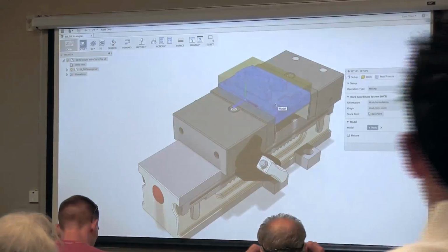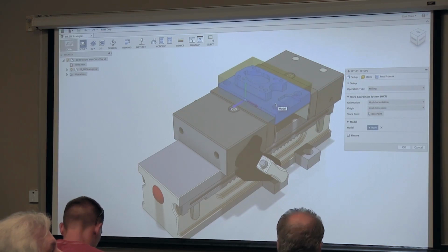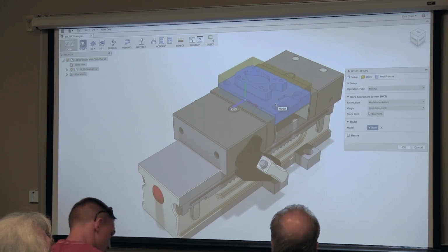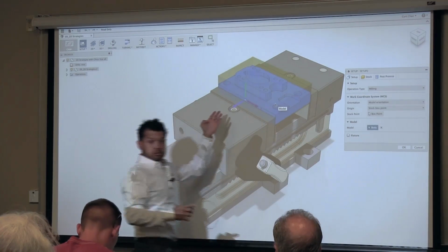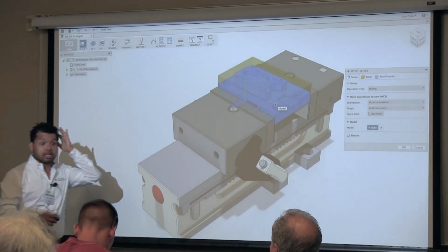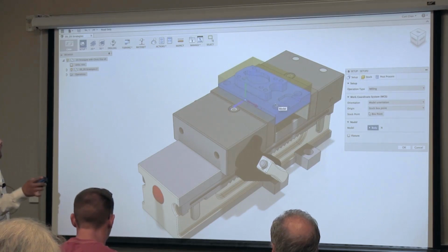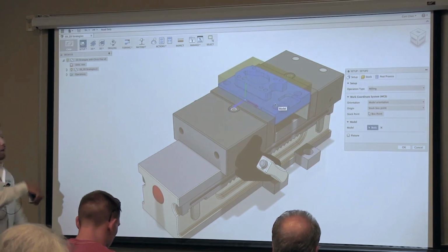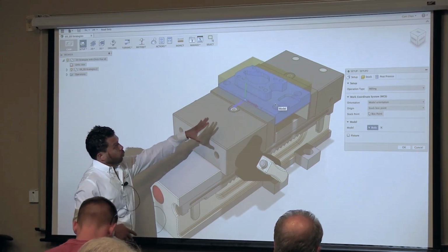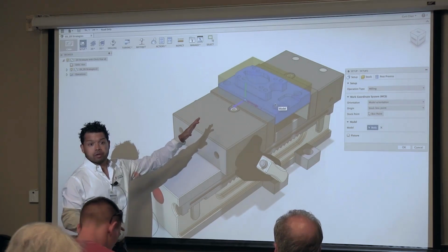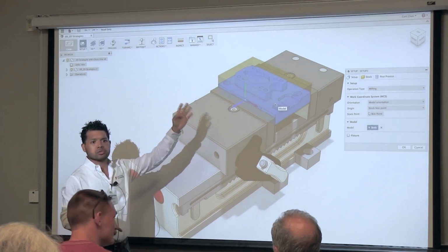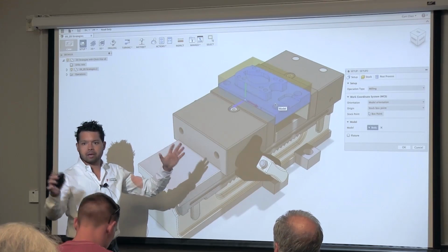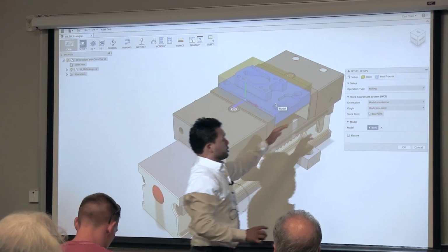So when we look at this now, this solves half of our problem, right? What else do you think is the next problem here when you look at it? Origin. Well, I have my origin. What's not, it's not the correct way where we want it, right? And where we want to tip off and where we want to reference off of. So where would Z be coming down from? Top. Left, yeah. And we can have it left corner, center, whatever, right? But today we'll just keep it simple and we'll work this way.